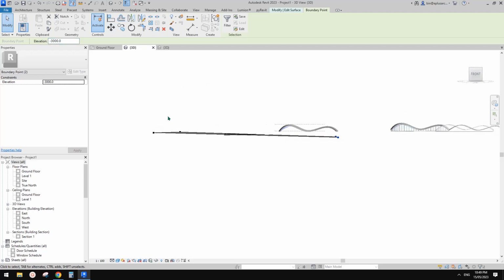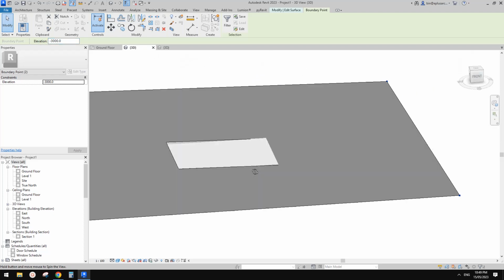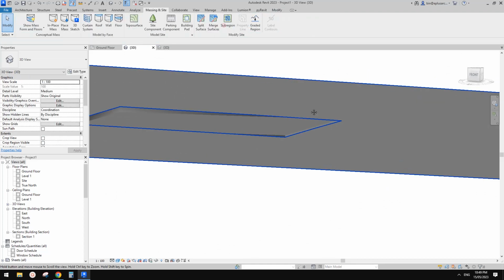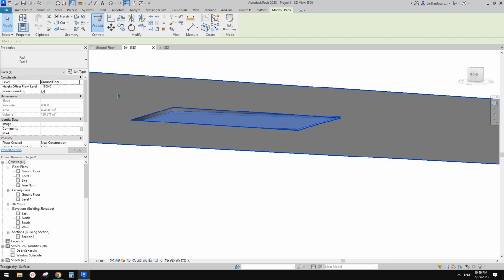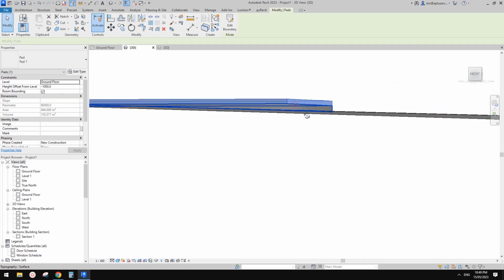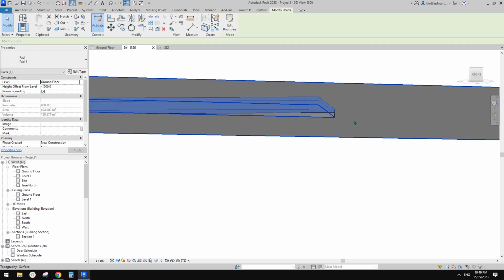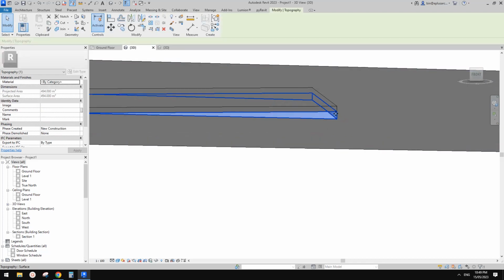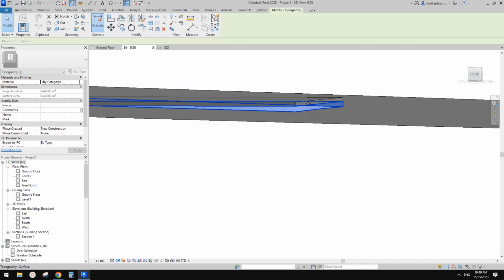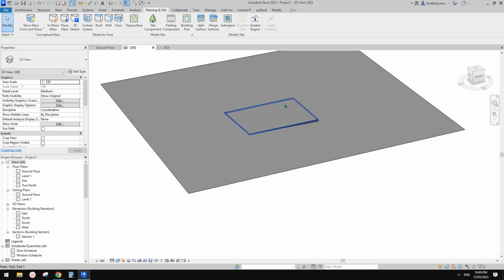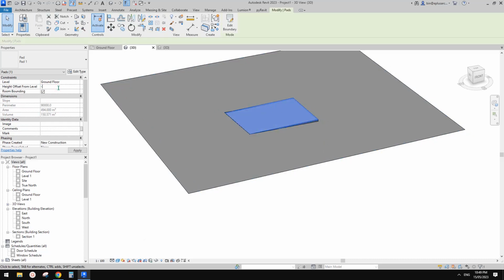So now you can see the whole sides become sloped, and anywhere there's the building pad is higher than the top surface, so let me just increase this a little bit, -1 meter. So you can see where the building pad is higher than the top surface, this will also fill this part to match the pad. Okay, so let's just move this down again.